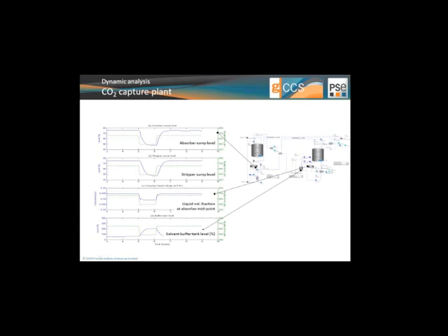Now, what is the origin of this disturbance? If we just monitor the different sump levels of the two columns, the absorber and the stripper, we will see that the holdups are shifting substantially between these columns. And in fact, they're all accumulating down in this buffer tank storage that is just underneath the, or you can see it to the left of the stripper sump.